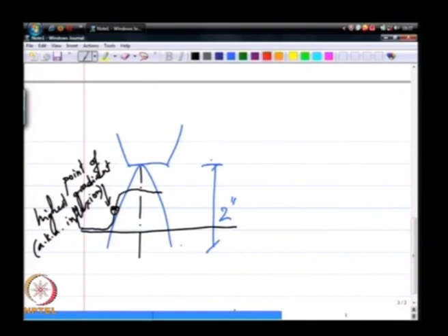and through a curve fit figure out what the cone angle would be. So, that 2 theta is calculated knowing what the spray width is here, spray width is at another axial location, and the fact that I have the nozzle here. Using these 3 points, using these 3 data points, one could essentially reconstruct the spray.